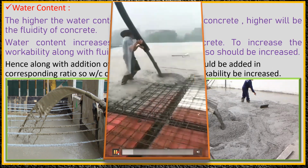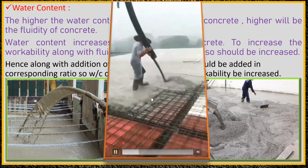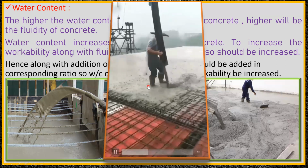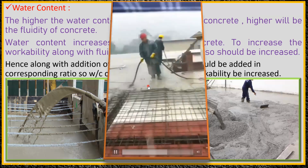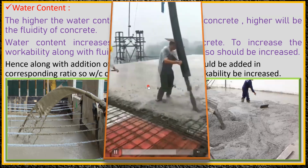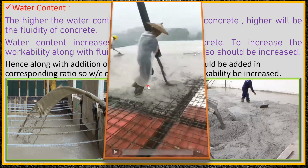Yeah. So you can see here, this concrete already has enough fluid, enough water in it, and this is a very good mix, right? But over that, what is happening now, there is a lot of rainfall happening. Now what is happening? Water content is increasing. If water content is increasing, now again what will happen? The strength of this concrete is going to come down, right? So you should not do all these things in the site during the execution, right?